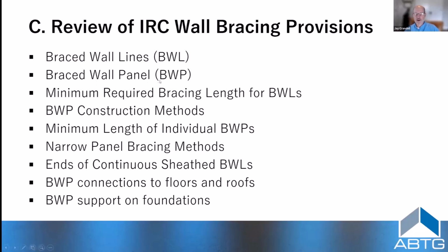And then braced wall panels are what you put in those wall lines. They're actually segments of wall. It doesn't have to be a panel material. It could be a let-in brace or whatever product or methodology you're using, but there's got to be a segment or a panel of the wall that actually meets the requirements to provide bracing in the braced wall line.